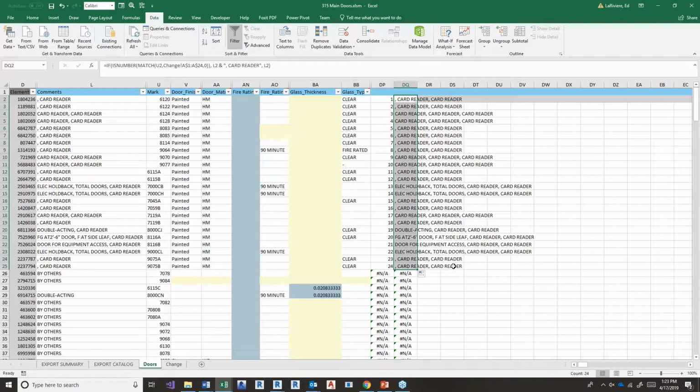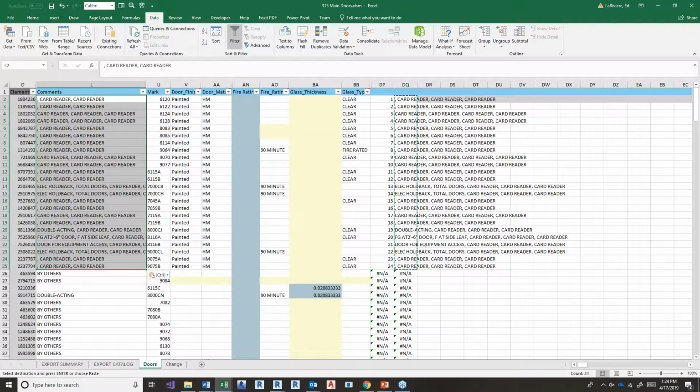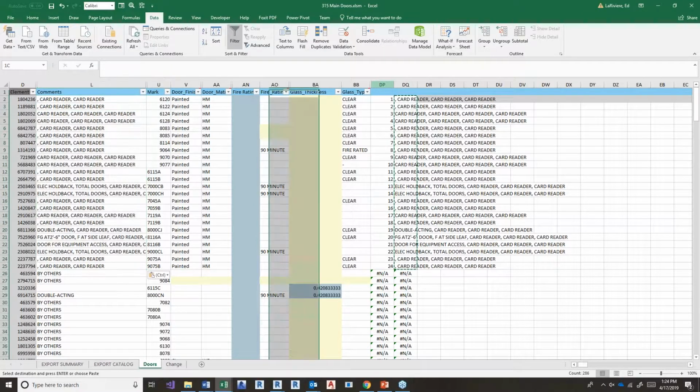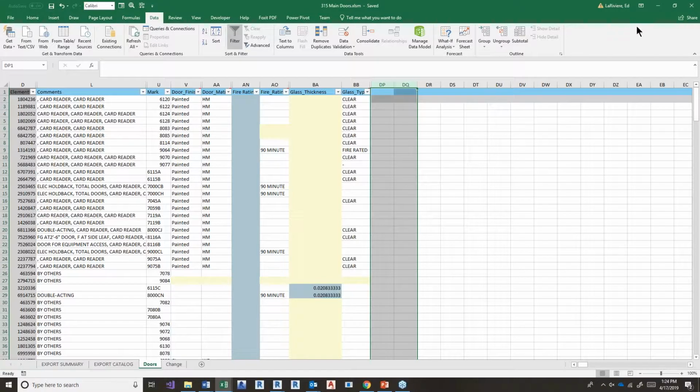Okay. So we can use Excel's match command to match information from an external source previously unrelated to the BIM model, and then marry it to a data source inside the BIM model. I can take the values now and copy them. I'm going to paste them back into the field as values. And of course, I would have to do some more formula wizardry to make this look nice. But for now, I'm going to delete out the formulas, save the file,